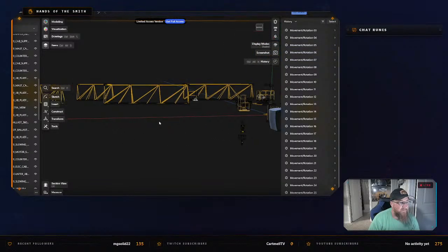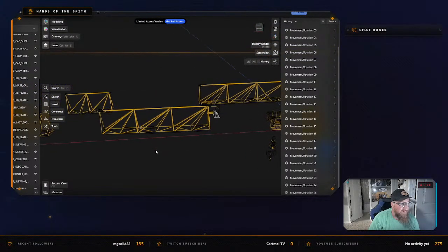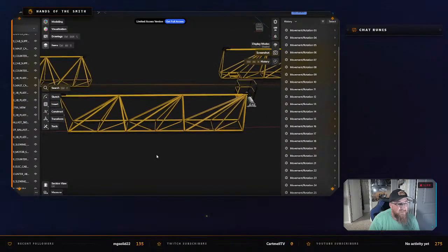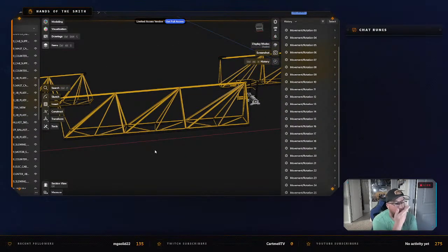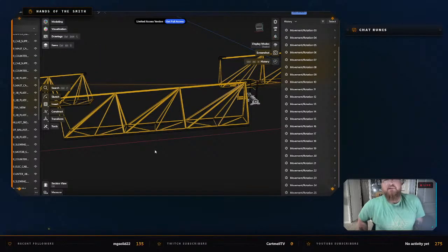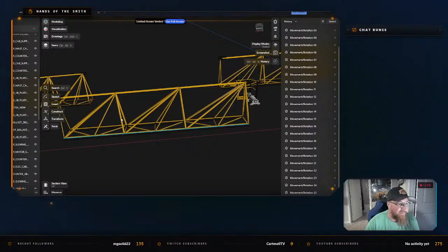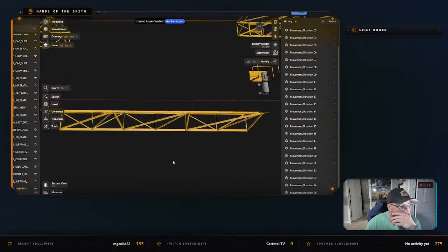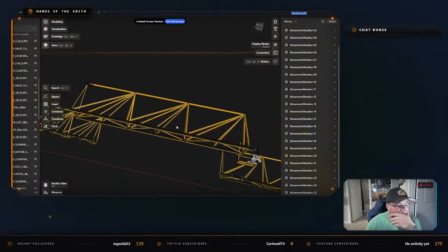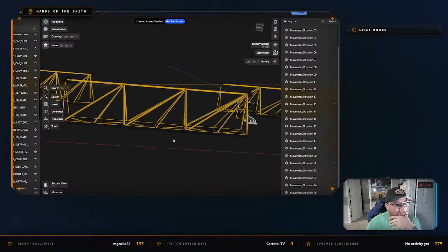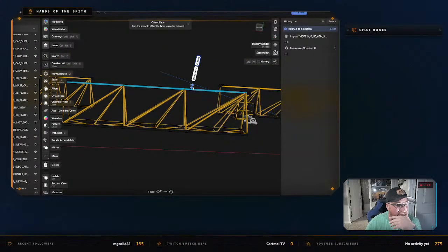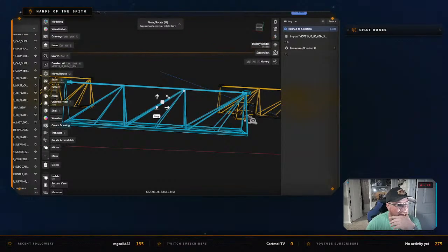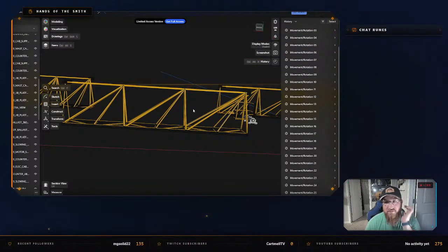I'm trying to think, when it comes to these jib pieces, how would you lay this out so it's not going to look absolutely ridiculous with the layer lines stepping up here as it goes? Can't really print it on its side. You'd be able to take this piece out, break that into its own separate object, right?